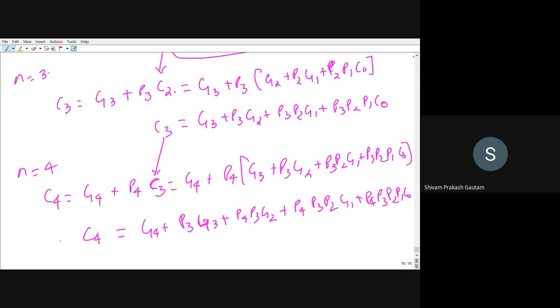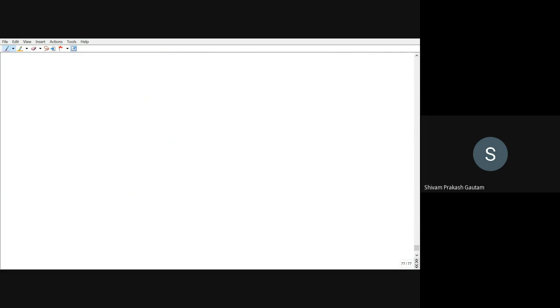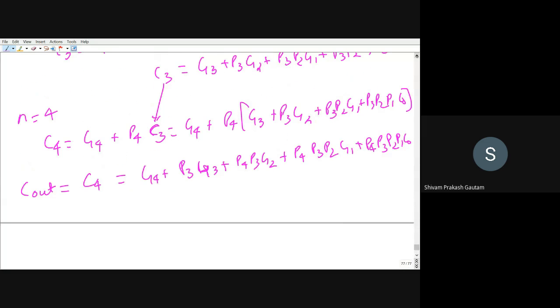That is the carry out. You can see this final carry out is not dependent upon the previous carry, but only dependent on the input carry. This Cout is only dependent on the input carry, right? So it does not have to wait. Obviously, some processing time has to be there to implement this G4 logic, right?